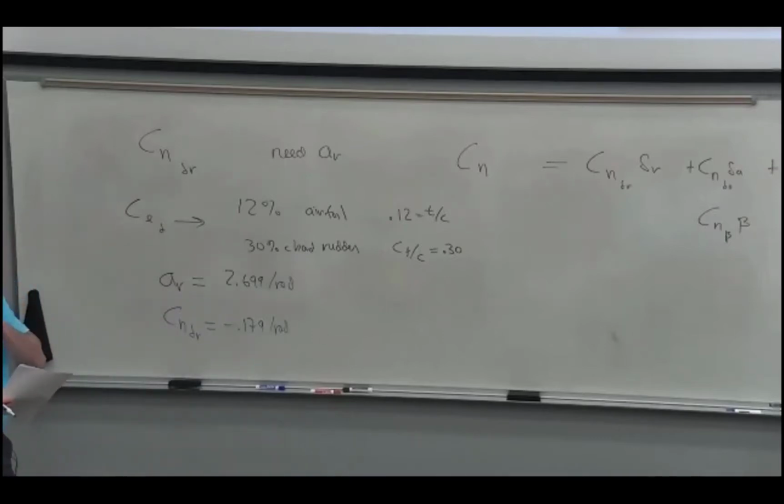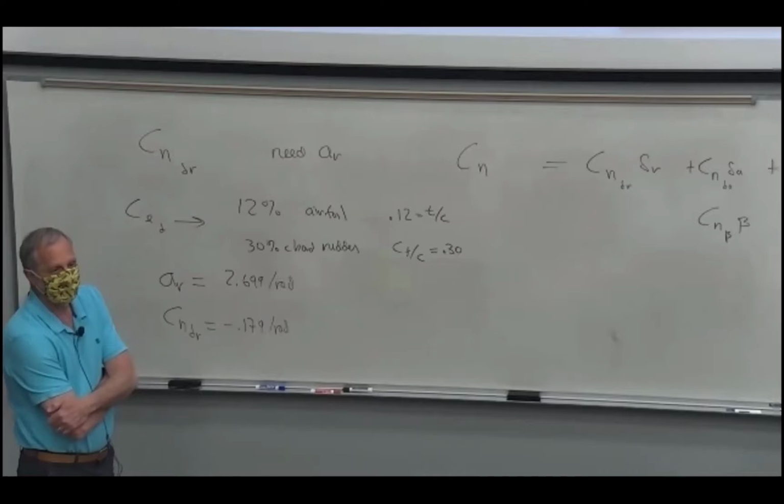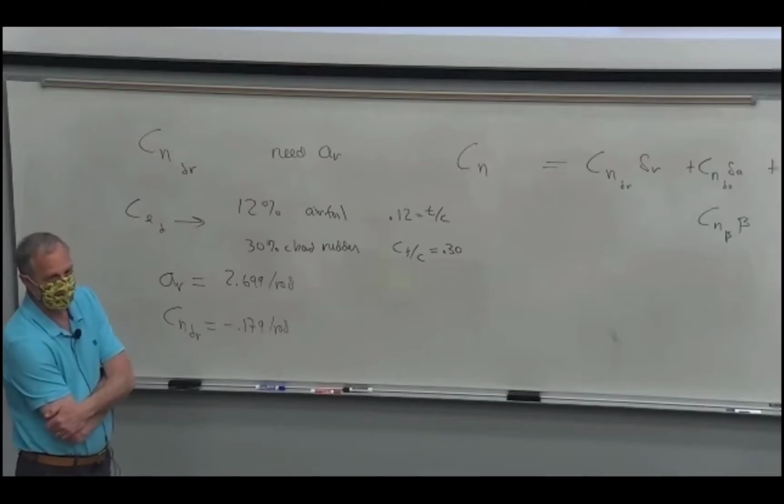And as you've seen before, these charts that you have to look stuff up, they're generic wind tunnel data charts. Notice that one contains a whole bunch of different airfoils in it. So you have to look up the airfoil thickness. So if you had a 0009, you'd look up the value for that, the 0.09.